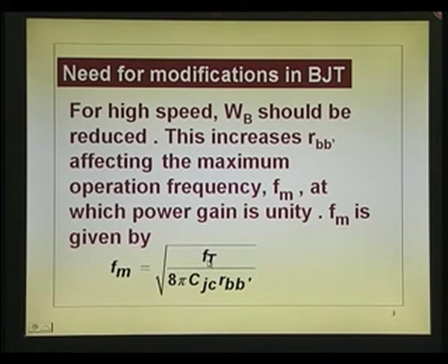You can improve the cutoff frequency by reducing the base width. So, that you can improve, but maximum operation frequency where power gain is unity is limited by Ft and also CJC, collector junction capacitance. You can reduce it, and if I have an n minus layer on the collector, automatically depletion layer width becomes longer and the CJC becomes smaller. RBB dash. So, the RC combination between the collector base capacitance and the base spreading resistance together bring down the maximum operating frequency. So, this is a general formula, I just borrowed it straight away, there is no point in spending time on deriving from the equivalent circuit.